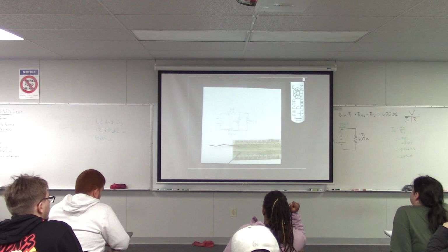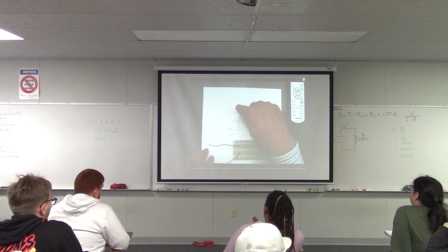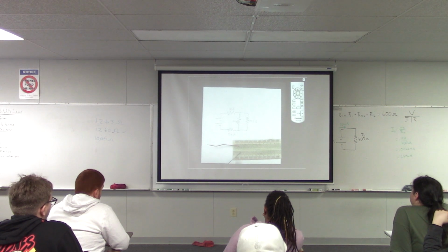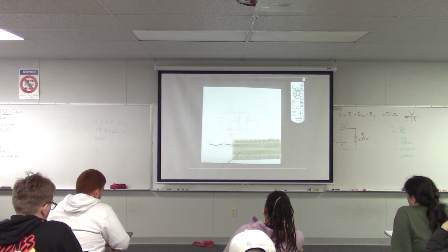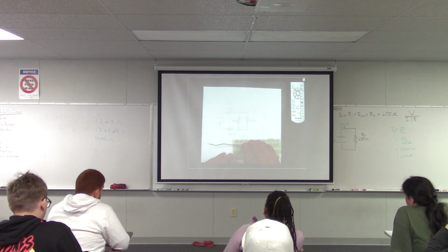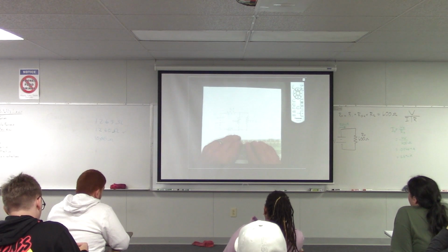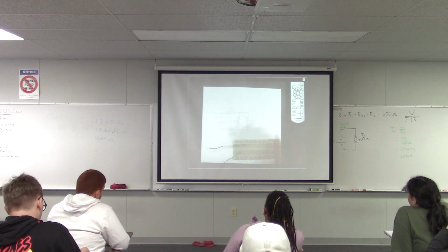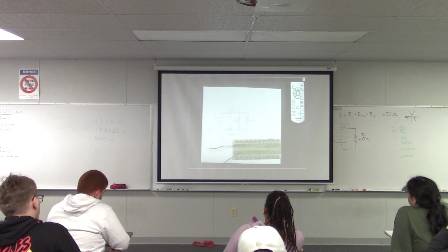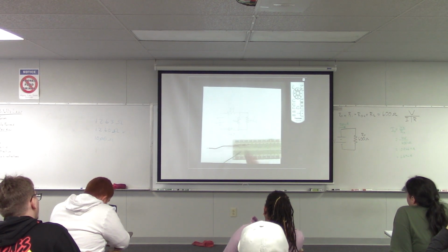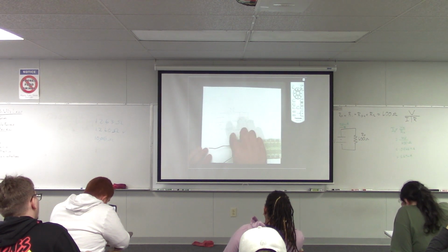On your actual test, you need to make sure that you take the 1 kilo ohm resistor and put it in the top spot on your circuit. Seems like it should go without saying, but people have said, well, I just put all the resistors in the board and it didn't work for me. Well, you put the 1 kilo ohm over here and you put the 5 kilo ohm down there, and yeah, you've got to put them in the right places, okay?